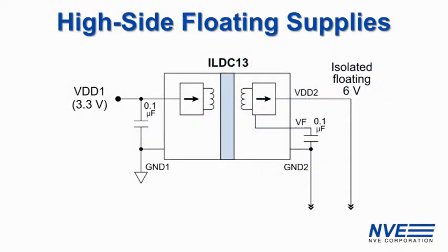We need two DC to DC converters to drive each of the high side MOSFETs. These DC to DC converters are fully regulated and require just two external components, two inexpensive capacitors, and no ferrite beads or other EMI mitigation.